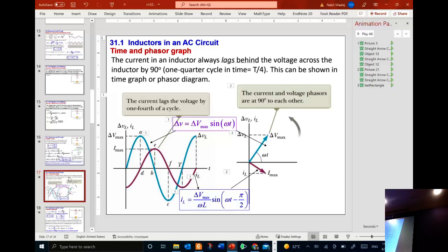Okay? So remember yesterday I said let's switch it. Now this phasor diagram actually uses a different convention from Serway. So normally you should have this flipped. This here is flipped. That's why I have written it not delta V_L. This is delta V of the EMF. This is the voltage across the EMF. Because if you switch the polarity, then this will be a minus sign. So it's delta V max sine omega t, which is the voltage at the source.